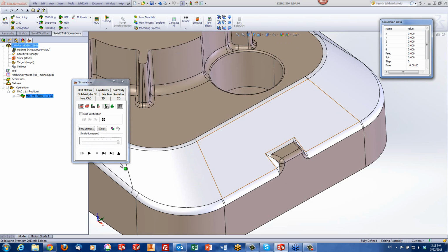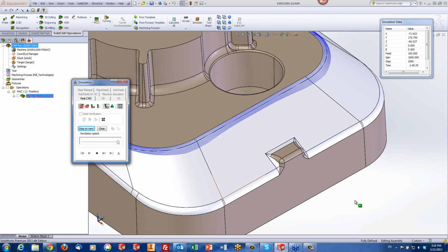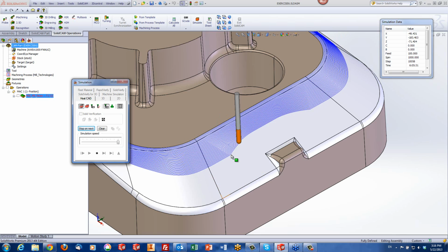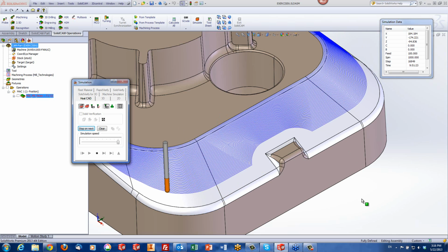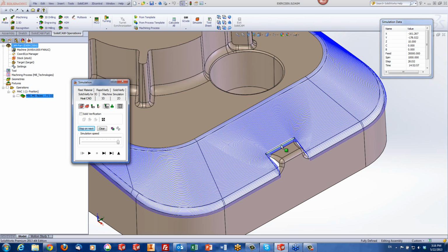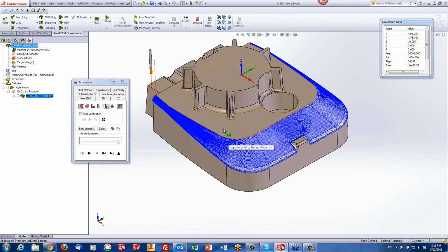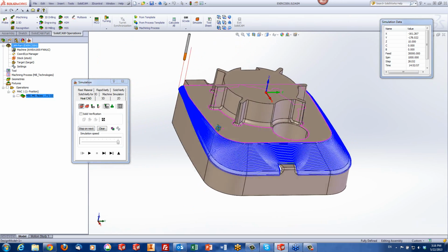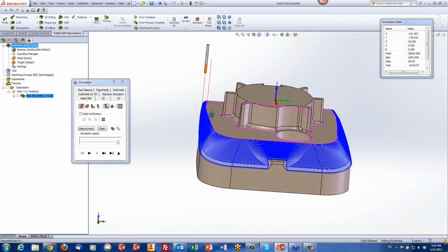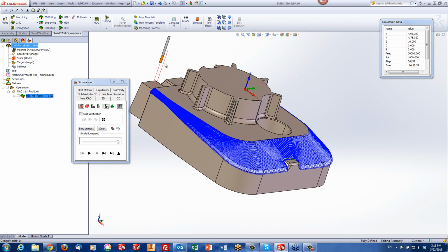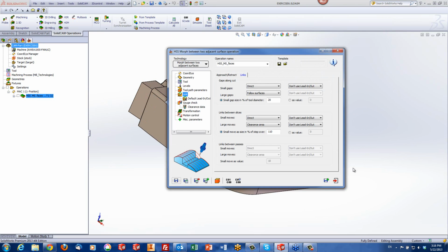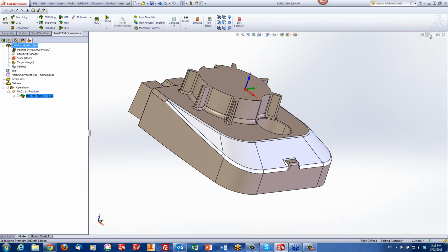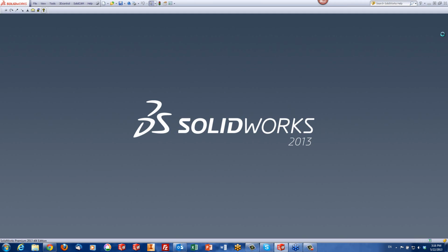And run the simulation now, and this time, again, you can see it changes its shape as it's going further down. And when it gets to the end, it'll actually follow its surface as shown over here. Note, this is really a perfect toolpath as we see it. Okay, you can see it from all sides. One entrance point, one exit point, and that's it. Okay. Now, let me run my next operation, my next part,